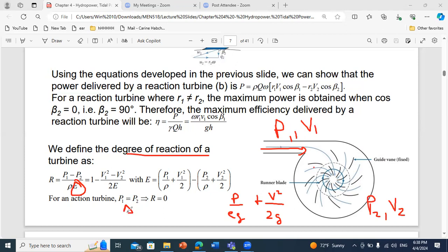So if I do delta P over rho, okay, you know, Bernoulli can be written in several forms. One of them is to write in terms of heads, or also you can write delta P over rho plus V square over 2, plus gz equal to constant.